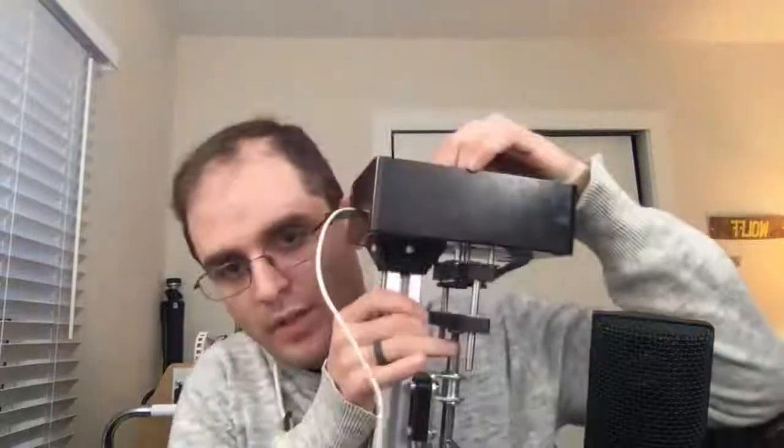So I have one of these nRF9160 Feather testers, and I always have an extra one in here. And what I'm going to do is grab this guy. Just to show you what's happening here, on any of these Nordic dev boards there's a jumper that basically forces it to use the external target, so it'll always provide power to that external target.